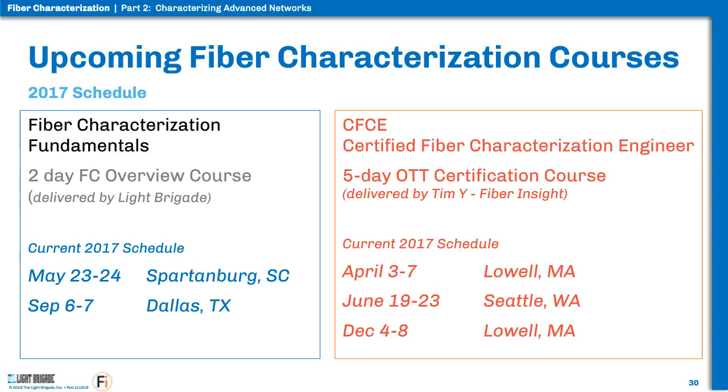Okay. Next question: is PMD due to ovality of the core, or the core plus the cladding? Well, if you think about glass, I use the term that it's made like the rings of a tree. When the glass is made, it's made on a lathe, so everything is pretty evenly distributed.